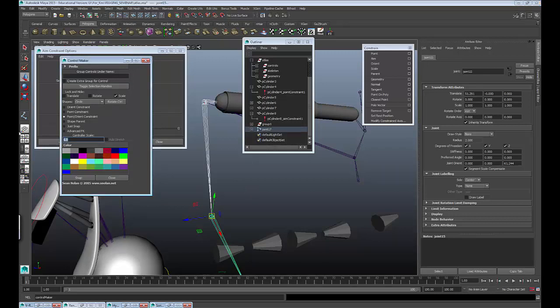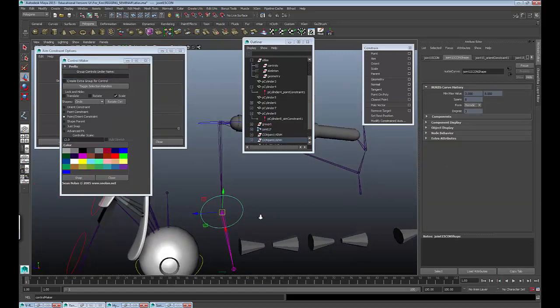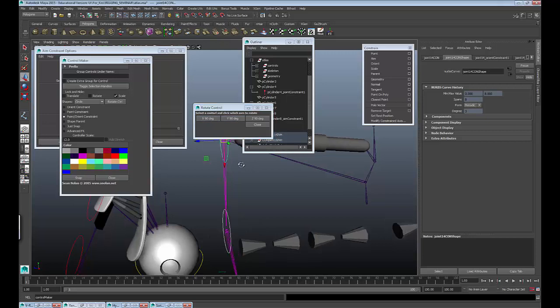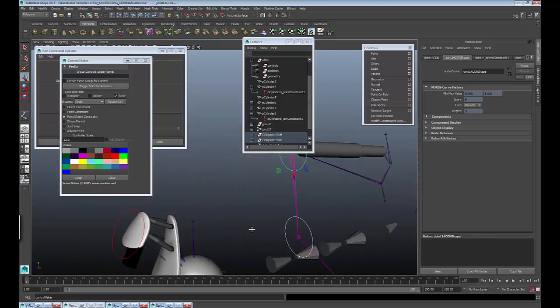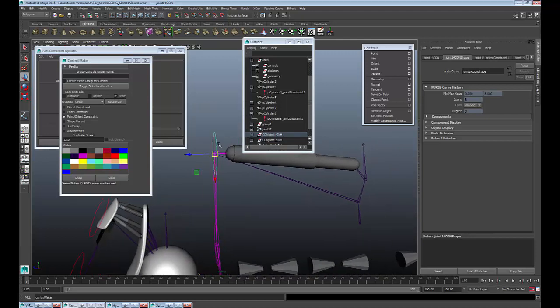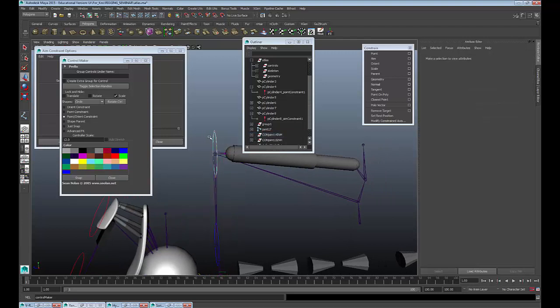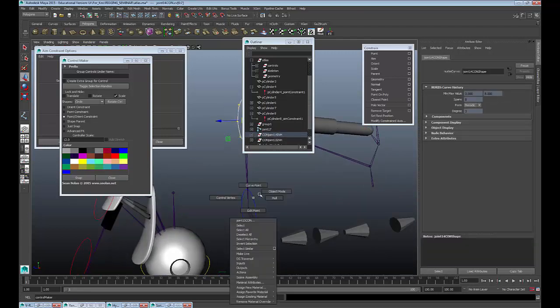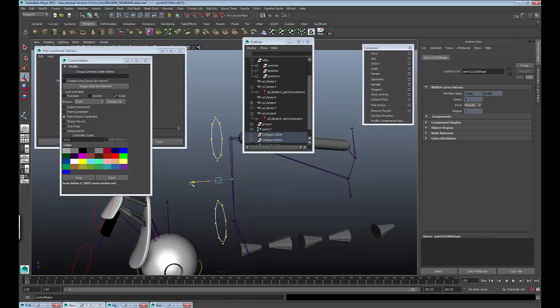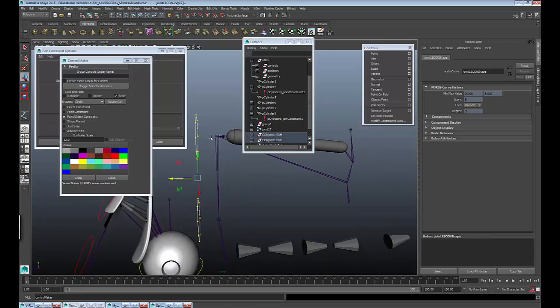I'm glad this is not working though, because oh no, it is kind of working. Okay, never mind. I was going to show you something, but it's not important. And then I'm just going to rotate this. Whoops, wrong one. There we go. And again, we can move these around, but you have to move them from the hull so the pivot point doesn't get changed. Because when you move it on a shape node level, the pivot point stays the same.